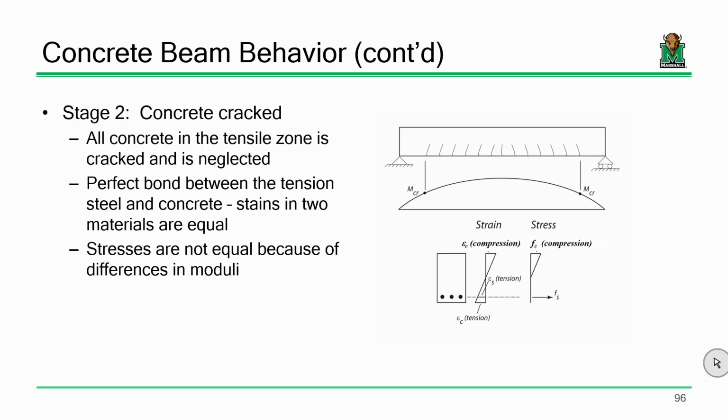What we've been talking about is we've taken a reinforced concrete beam and asked ourselves, if we take that beam and start amping up the load, how will that beam respond? We've already assessed one of its responses: the beam will remain uncracked until the tensile stress reaches a certain point, and we term that f sub r, the modulus of rupture. And we've done a series of examples looking at how the beam responds elastically, or how it will respond until we reach the cracking moment.